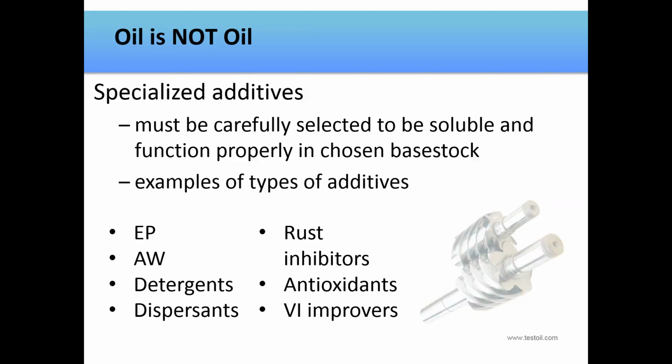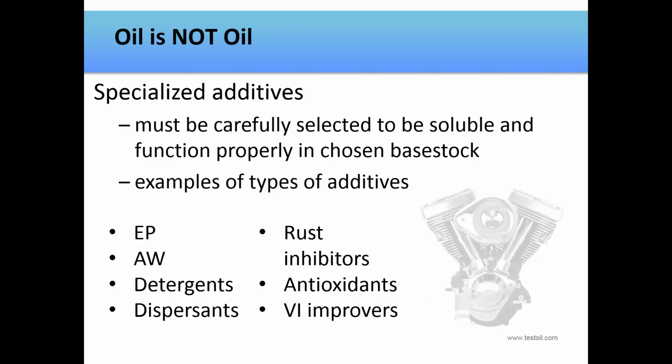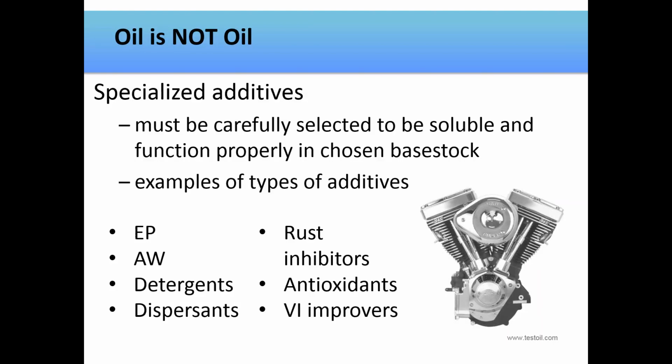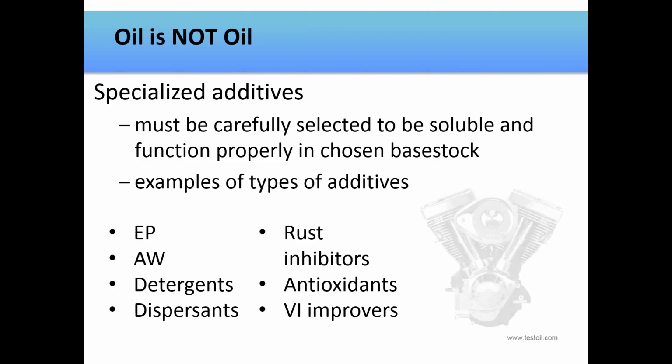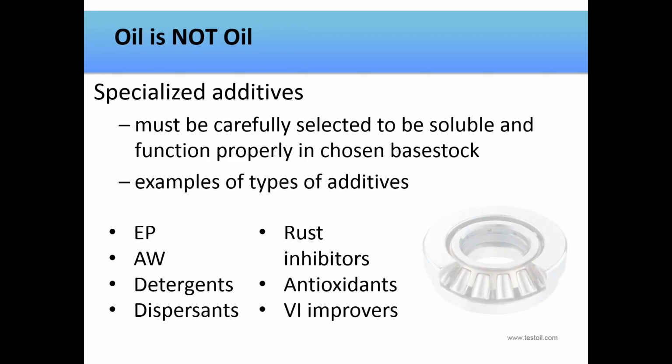And lubricant manufacturers spend many years developing a lubricant. Additives are typically used by application. So for example, we have gear oils that use EP or extreme pressure additives. These typically contain phosphorus, while turbine oils are often formulated with amine and/or phenolic antioxidants.